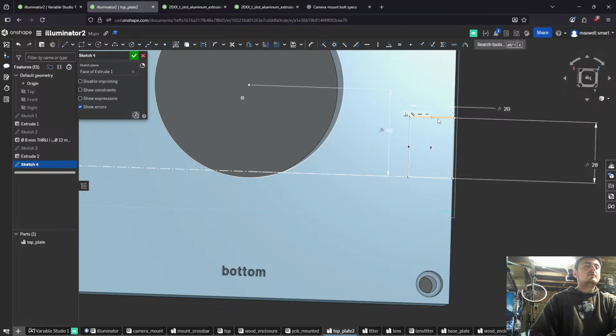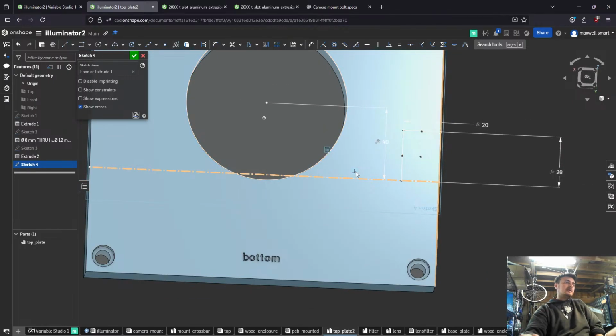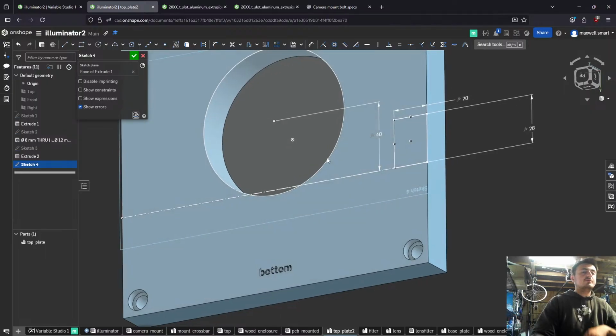It's like, well, how far would we need to move this so that we could clear it? We need to move it a lot in, and I'm wondering if that's the right thing. The problem is that we want to have a bolt that has a nut that we can really clamp down on. But I'm wondering as opposed to tapping this PLA, because PLA is just so damn weak that this thing's going to collapse and I'm going to cry.